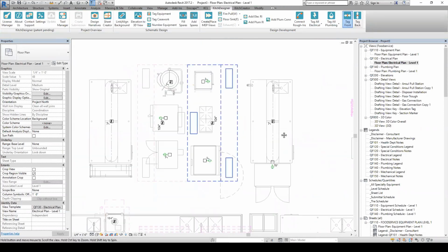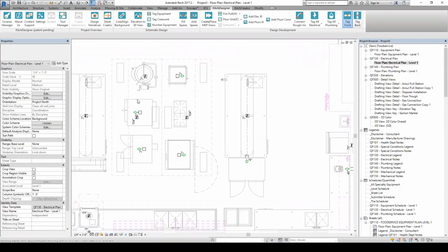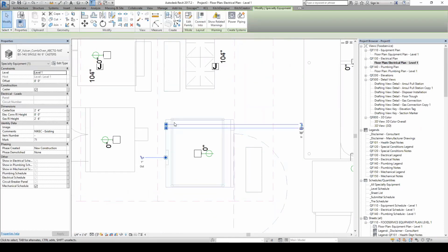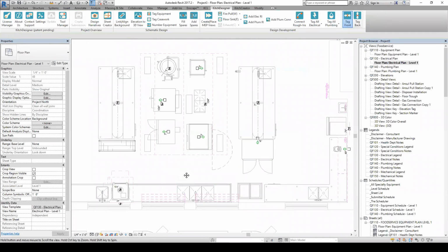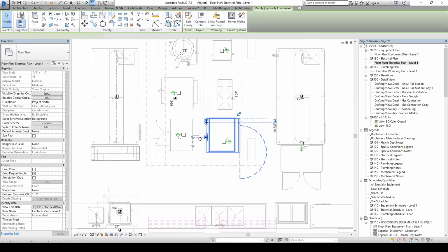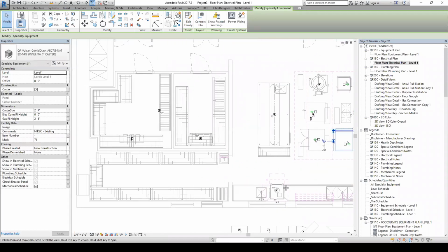So the other half of the roughin tool: wall roughins usually get placed in the wall, and I have my stub ups set to just be placed in the center of the piece of equipment. In that instance, we're taking the piece of equipment, figuring out the total bounding box of the geometry, and then calculating the center point and placing the roughin there. But you can choose these locations in settings. You don't have to place it in the center of the equipment. You can place it in the center back, back left, back right, back center right, back center left. You can see some more here.